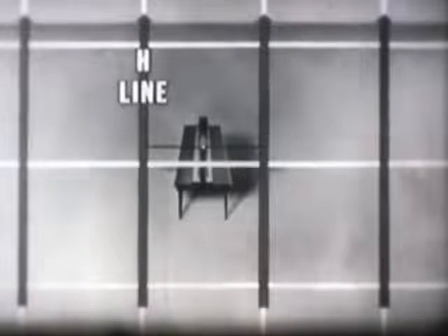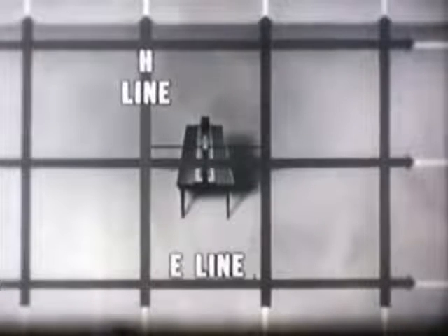It stretches, yet the magnetic and voltage lines retain a fixed relation to each other and to the Earth. For instance, stopping the wave, we see that the magnetic or H lines are still perpendicular to the voltage or E lines. Also, we see that the E lines in this wavefront remain horizontal or parallel to the Earth's surface. Because of the direction of the E lines, we say that this wavefront is horizontally polarized.